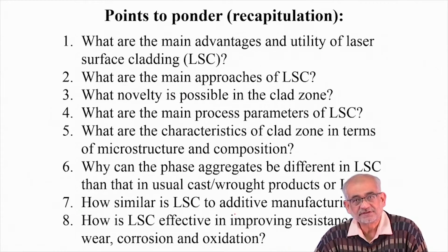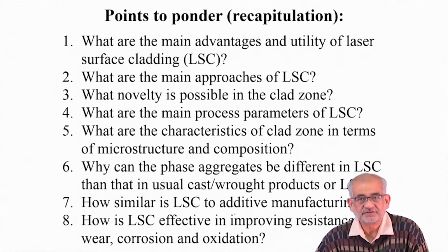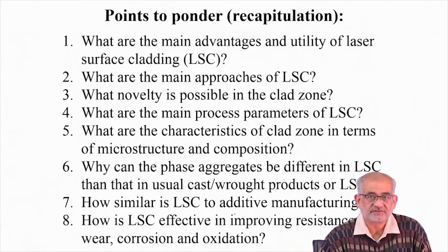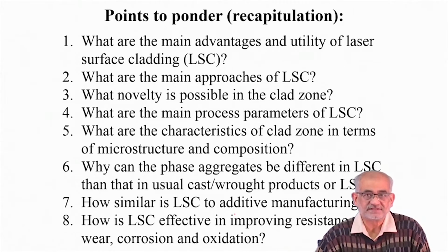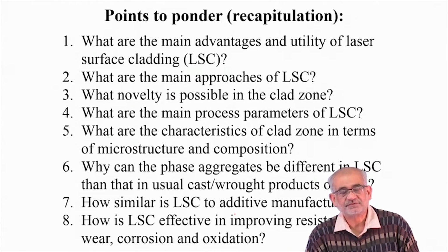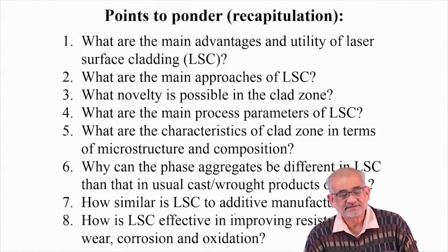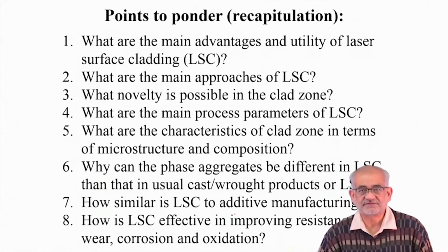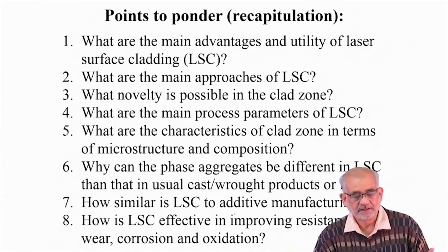Or in other words, on the other extreme, if we want the same alloy to be overlaid on top of an existing substrate for repair job, for reclamation or dimensional restoration, we can even do that. So laser, irrespective of what we are feeding, can melt and create an overlay which could be fairly thick, and in fact it could be much thicker than what is normally possible in case of surface alloying or other approaches.